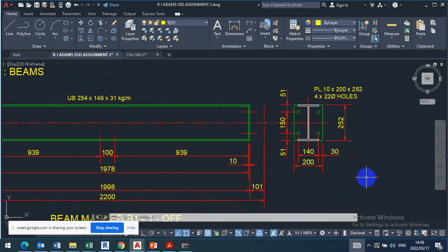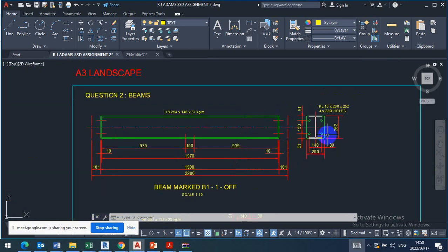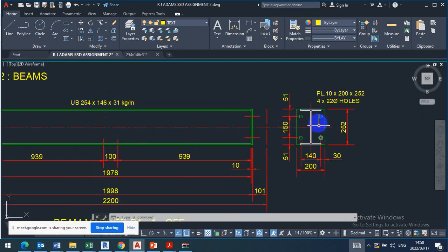Isn't he supposed to have a sectional view also available for you to see section AA on the side? No, not necessary. They only want to see the ends, the end plate detailing, not sectioning. You know the reason I brought this I-beam here: it will be in hidden detail if you look from the right-hand side, because it's behind the end plate. You understand? Correct, yes.